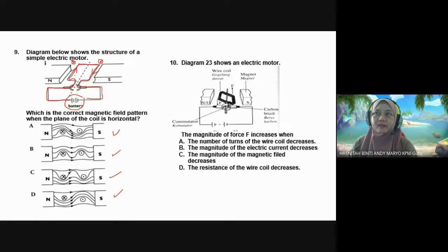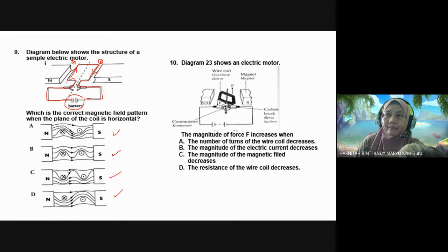So your middle finger pointing in because the current on the left is inwards. Okay. And your index finger pointing to the south. So where is your thumb pointing at now for the left side? Pointing down. Okay. Here you will find F is acting downward.